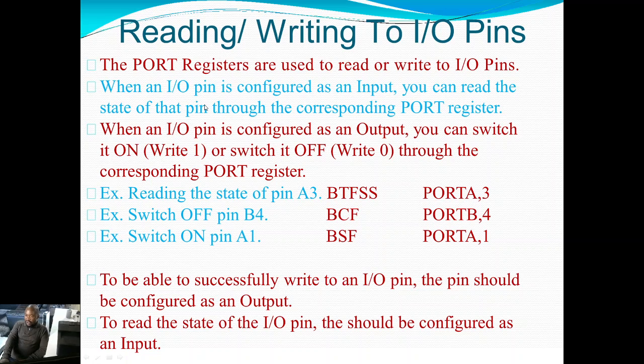When an I/O pin is configured as an input, you can read the state of the pin by accessing the corresponding port register. When an I/O pin is configured as an output, you can switch it on or off through the corresponding port register. And remember, to access the port register, you must be in bank 0.